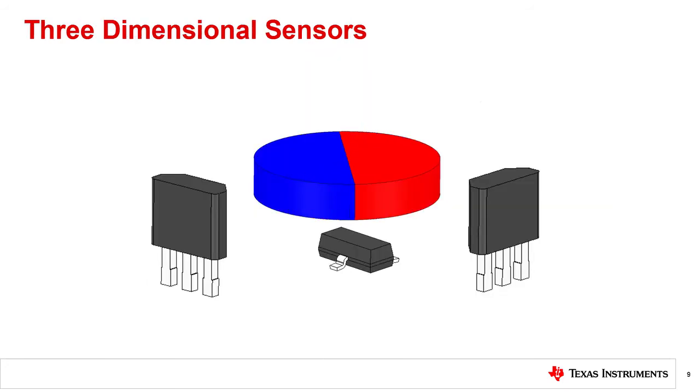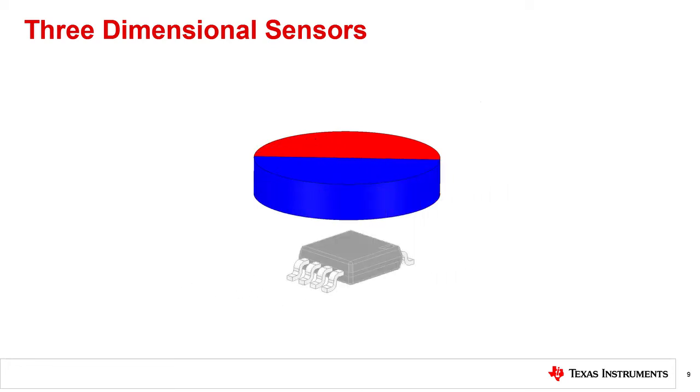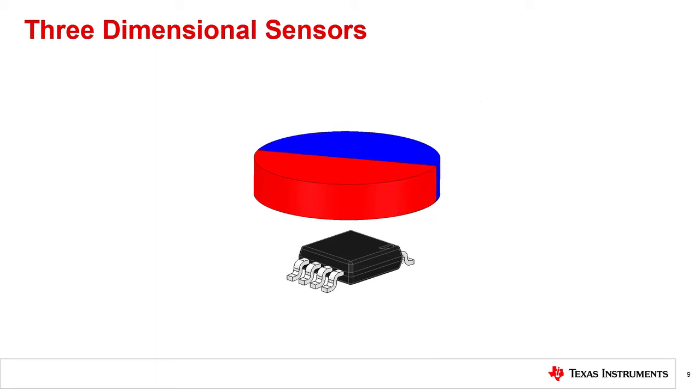If we were to integrate three mutually orthogonal Hall elements into a single package, we can limit variation between sensors and maintain a fixed 90-degree mechanical separation while also allowing one device to detect all three components of the magnetic field. In the case of the rotating magnet shown here, the X and Y field components naturally maintain an ideal 90-degree separation. For devices which also integrate field vector normalization, the sensor can be placed virtually anywhere the field may be practically measured, making them widely adaptable to their mechanical environment.